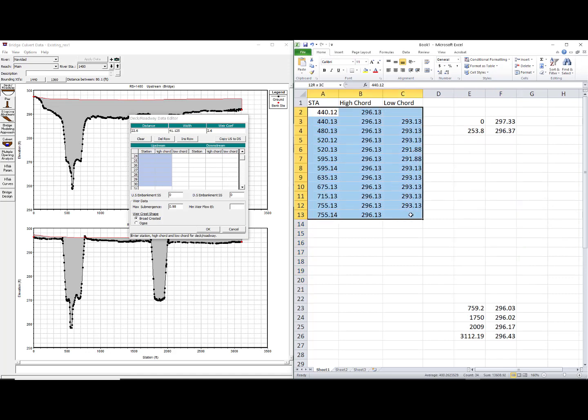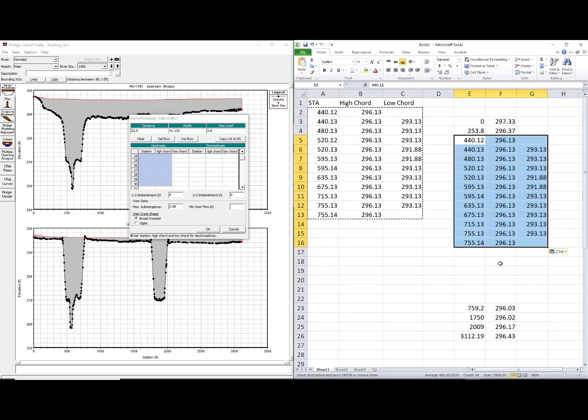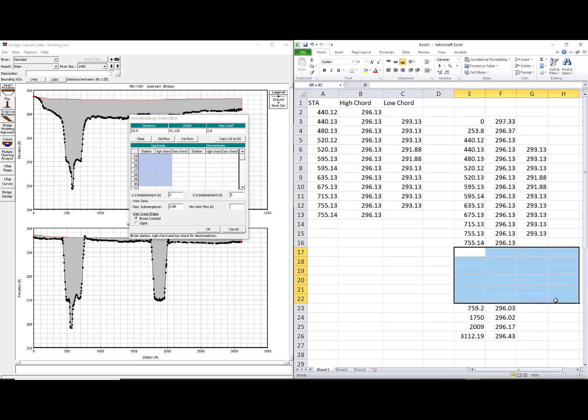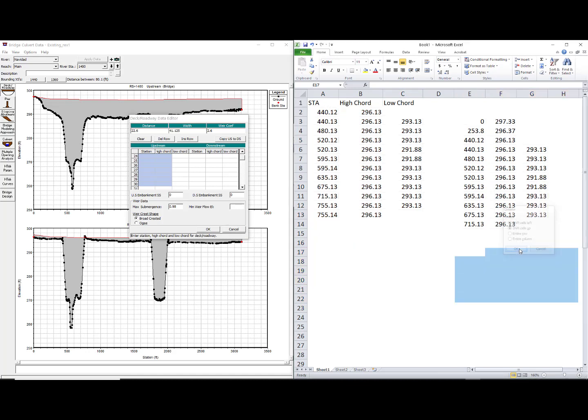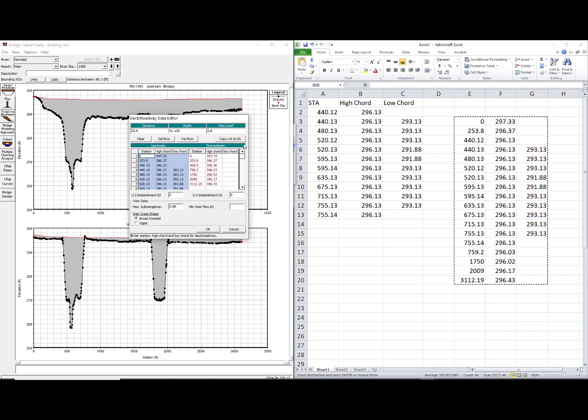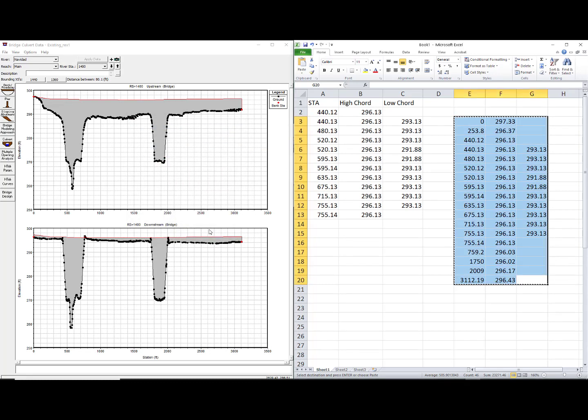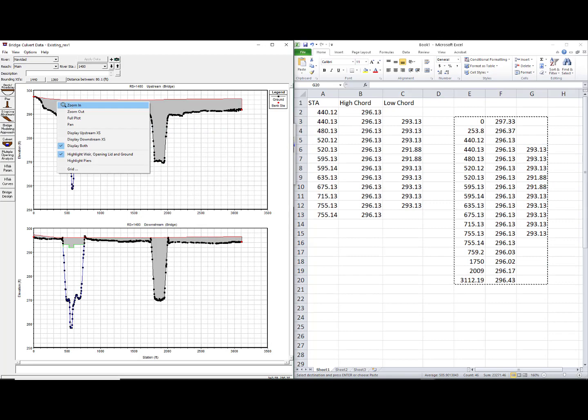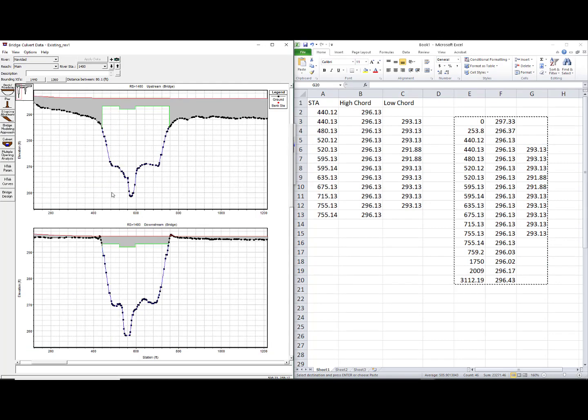and we'll just copy these and we'll stick them in. So now we can come back and delete this to clean it up. And now we've got appended road deck data. We'll just copy and we will paste it into the road deck to overwrite it. And we'll make sure we click this button that says copy upstream to downstream, and we'll say OK. And there's our road geometry, our opening area.